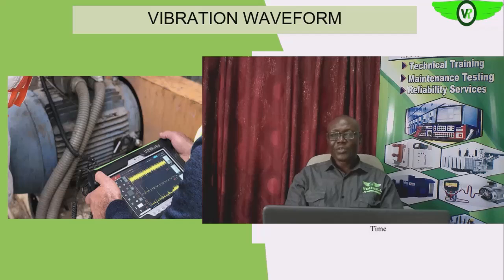So if we are able to identify the frequencies at which the vibration caused by the rotor, the one caused by the bearing, then on the pump side, the one caused by the bearing at both ends, and the one caused by the impeller itself, which will be the number of vanes on the impeller times the speed of rotation. That is the fundamental frequency.